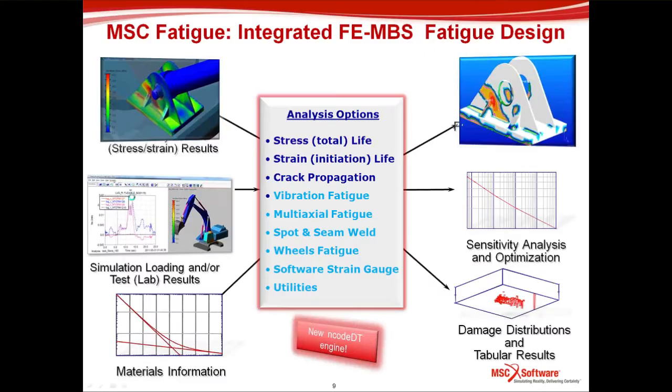So when we mention MSC Fatigue, we like to stress the fact that MSC Fatigue is an integrated FE and MBS fatigue design solver. The diagram shown here shows the workflow with the other players in the CAE arena. You have input shown to the left. This includes the material information, the loading that is often extracted from ADAMS, as we have seen during session one, and the geometry and finite element description of the part.